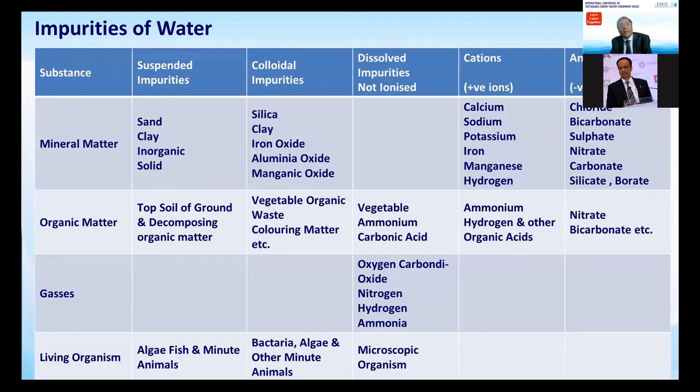And the impurities which are colloidal and suspended are removed by physical treatment. We have filtration in sand filters, activated carbon, multimedia. If we have arsenic or fluoride, we can use the respective media for their extraction or adsorption as well. And for the dissolved impurities, we have to go for the membrane technology, which is very popular nowadays. Companies like Dow, Hydranautics, and others are manufacturing good quality membranes for various applications.